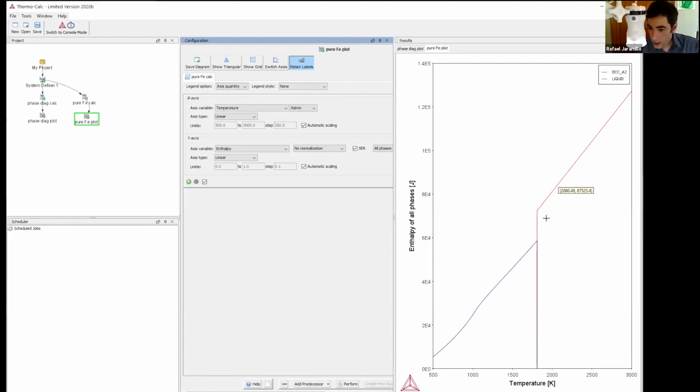Okay, how do I estimate the transformation enthalpy? That is the enthalpy of melting iron from this plot. Does anybody know how I would do that easily and quickly? Maybe enthalpy over temperature. Like heat over temperature, which is like enthalpy here. Well, the y-axis is already enthalpy. So how do I measure the transformation enthalpy? We go to the temperature at the melting point and take the two values.